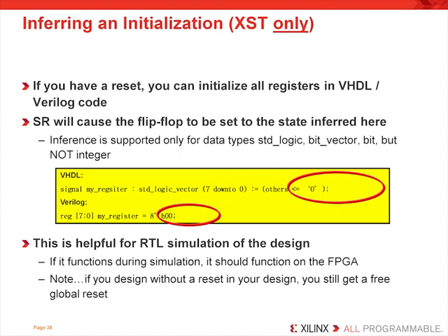Synthesis tools do react on this code. In this case, XST will place an init attribute of 0 on each flip-flop, which will assure that upon activation of the GSR, each flip-flop will go to 0. Most people assume that this is unsynthesizable code. It is synthesizable and it will affect the initial value of the register. But even more importantly for the customer, it means that when you do a functional simulation, you will have a known design. This is one of the biggest reasons that customers use for initializing their behavioral code.